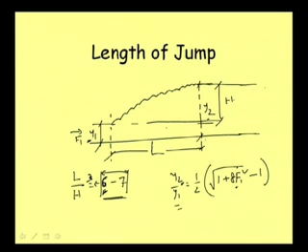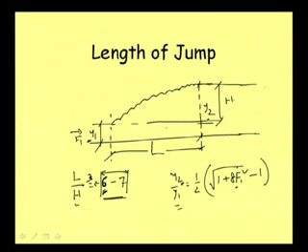Similarly, some relations give us an idea about this ratio when the slope of the bed is changing. So this information can be used when we are observing a jump in the field and want to know its length. In general, the length height ratio can be considered as 6, so length is equal to 6 times the height of the jump. This can be used in general.